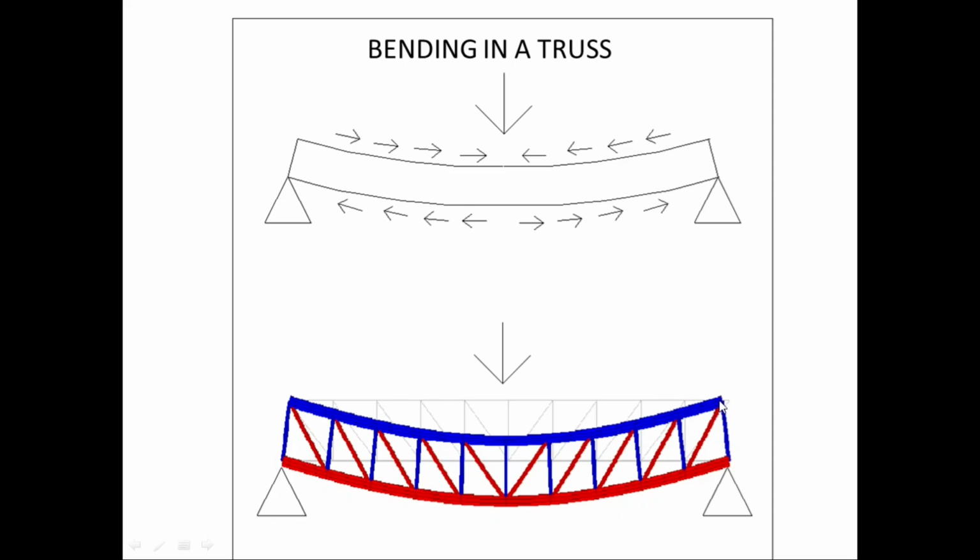I'll go into a little bit more detail, but if you've got a very large span, of course, and you want to keep the top compressed area as far away from the bottom in tension as possible, but you don't want a big heavy beam, you don't want that one big solid object, you can separate the two, the top rail as we call it and the bottom rail, with these little rods, which are all in compression, and these are bracing it, just triangulating it to stop the two sides, the bottom and top, from shearing away from each other.